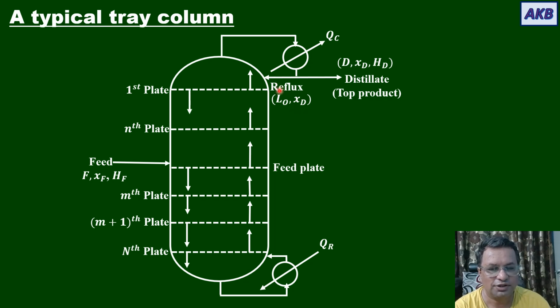After entering the column, the reflux stream flows down, and operation continues in this way. Feed is continuously entering, it is continuously taken to the reboiler, vapor phase is continuously created, the vapor phase continuously flows upward into the column, then is taken out at the top and sent to the condenser, then you have the reflux stream and the distillate stream.